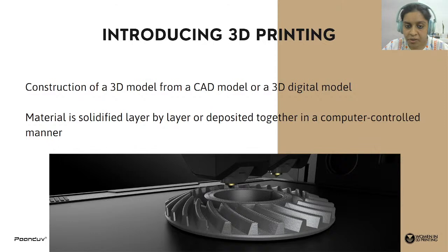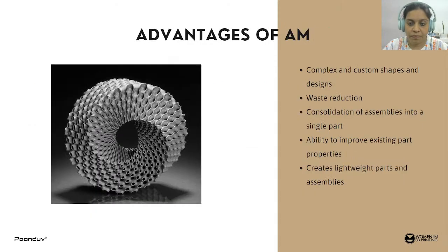You take the raw material. These raw materials are solid particles, or solid polymers. When they are subjected to certain heat treatment, they are melted and fused with each other to give a desired shape. This process is repeated again and again until the part is completed in a computer controlled manner.